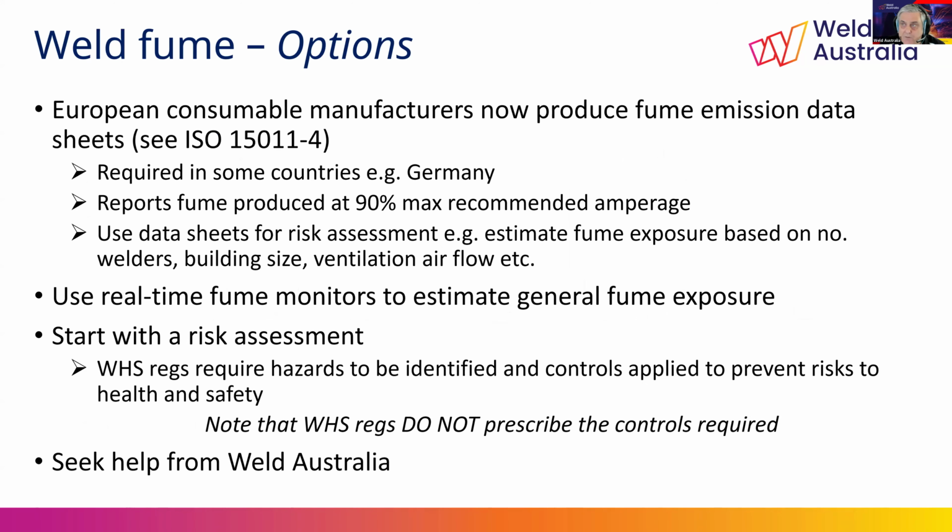Now, despite all this doom and gloom, I will answer a question in a minute on this one. Okay. Despite all the doom and gloom, there are some options available to users of the welding processes. In some European countries, there is a requirement to produce fume data sheets based on 90% of the maximum recommended welding current. There are no currently universal requirements as far as we're aware, but definitely in Germany and other countries with a fume limit similar to Australia.